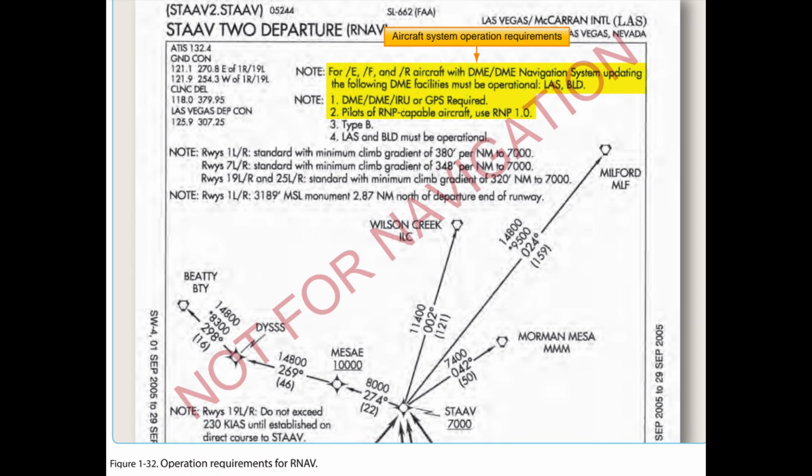There are specific requirements, however, that must be met before using RNAV procedures. Every RNAV departure chart lists general notes and may include specific equipment and performance requirements, as well as the type of RNAV departure procedure in the chart plan view. New aircraft equipment suffix codes are used to denote capabilities for advanced RNAV navigation for flight plan filing purposes.